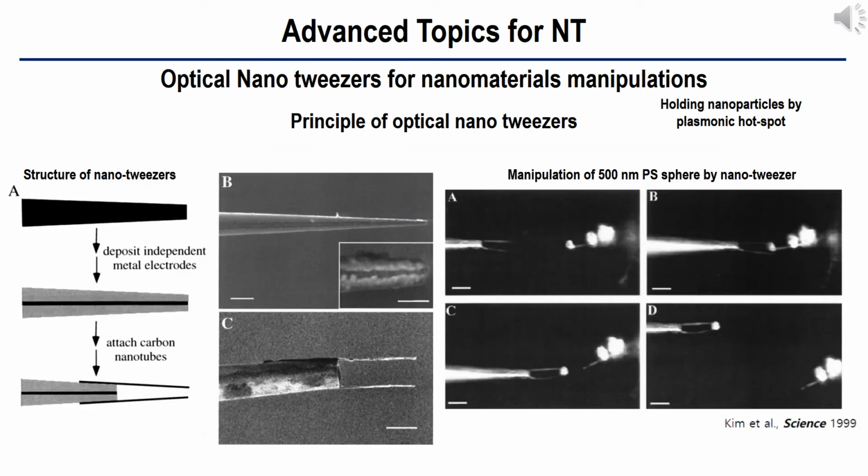Now, I would like to introduce some advanced technology to control nanomaterials. In the era of nanotechnology, it is important to manipulate and control nanoparticles. The nanotweezer is a nanoscale tweezer with a pair of long nanotubes on the surface of a metallic microtip. Using the nanotweezer, mechanical manipulation and interrogation of polystyrene nanoclusters can be done at the nanoscale, down to 500 nanometers. However, nanotweezers can have problems releasing the nanostructures when opened, due to the dominance of van der Waals and electrostatic forces.